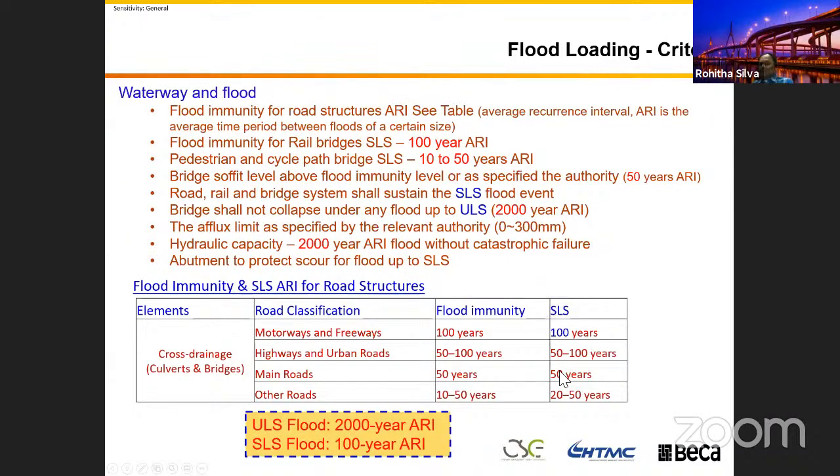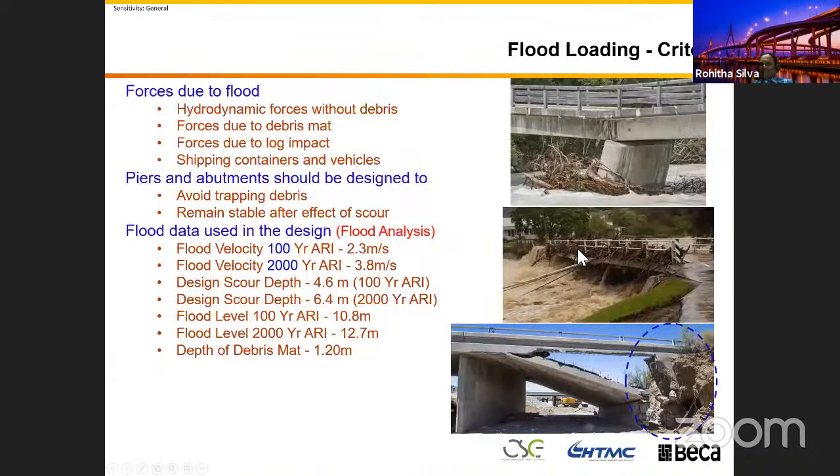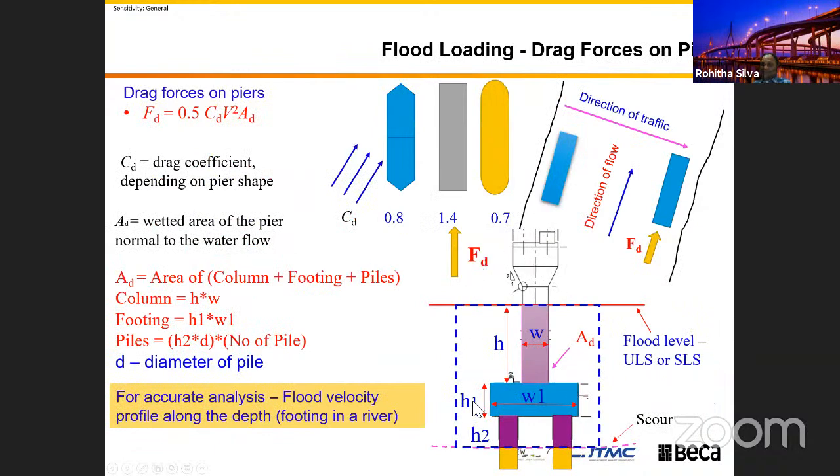As we know, like air, when there is a massive flood, what happens here? In this picture, you can see the bridge elevation, the cross section I have put in here. I have a yellow color right at the bottom. That's the pile, below the cover depth. I have this line as cover. Before the pile, normally up to the top of the footing, we protect with this cover, or else normally we put the foundation half a meter, at least half a meter or 1 meter, below the ground level. So this whole thing is gone.